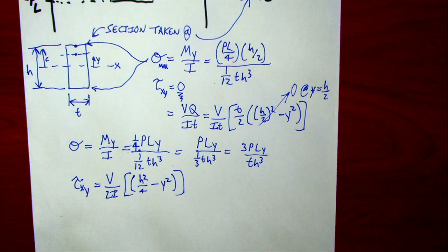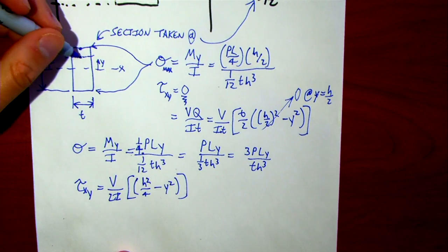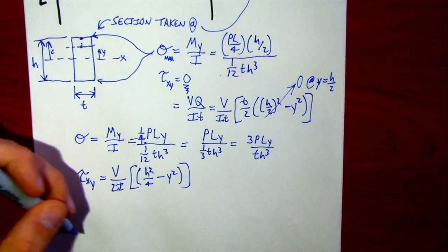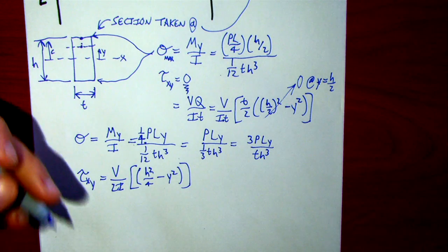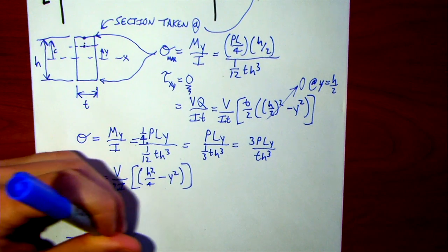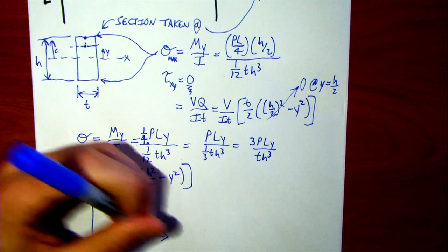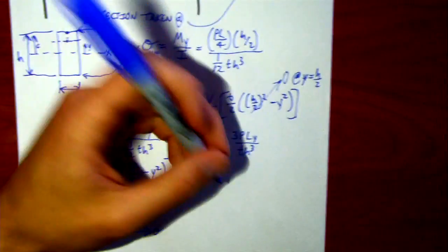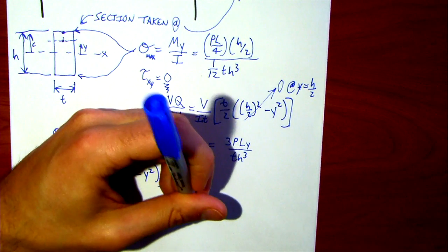We got two forms of stresses acting on that same point. So if you wanted to say, okay, what is our maximum stress? We have to construct a Mohr circle out of this. So we know the usual gig here: in order to construct a Mohr circle, we need to know a center point and we need to know a radius, right? So we know the center point is just sigma average.